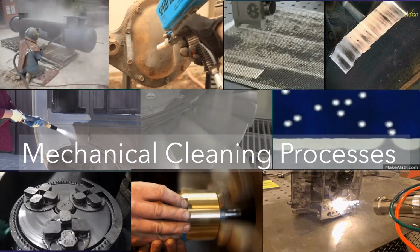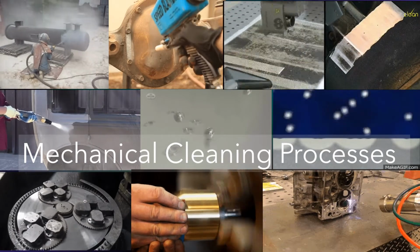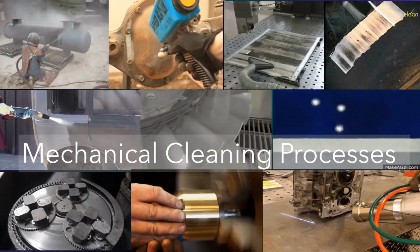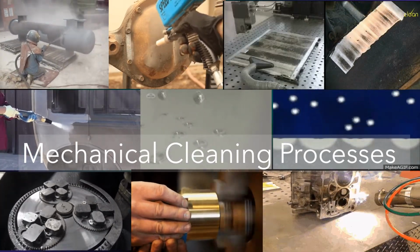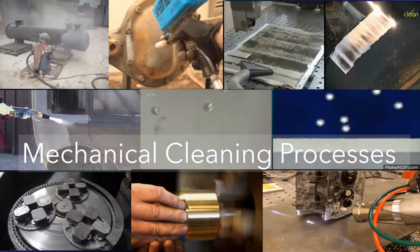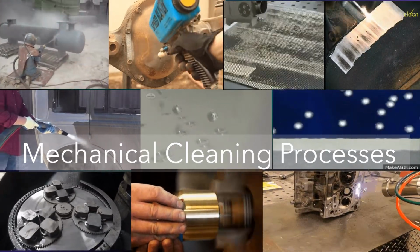The mechanical cleaning processes are a physical removal of soils, scales, or films from the work surfaces by a pressure or similar mechanical action. Often serves other functions also, for example deburring, improving the surface finishing, and surface hardening. The processes include blast finishing, shot peening, and mass finishing operations.